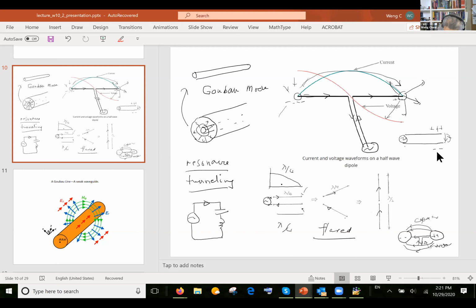And if he gets a bigger capacitance, then this can be approximately modeled as an inductor in series with a capacitance, okay? And this inductance can come from the wire here, and the capacitance can come from the two spheres. The two spheres can have fringing fields interacting with each other. If you make the spheres bigger, this fringing field capacitance becomes bigger. And it has this LC tank circuit, essentially, that allows him to drive current into the Hertzian dipole that was very short. Okay? Does this answer your question?